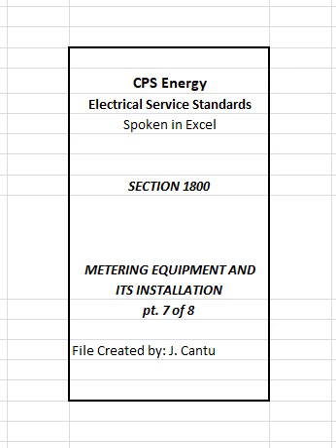2. Identification must be permanent and be applied by means of stencils and black paint. Use of chalk, ink, crayon, tape, labels, permanent markers, etc. is not acceptable. CPS Energy will not install meters where address identification is missing or does not meet the requirements